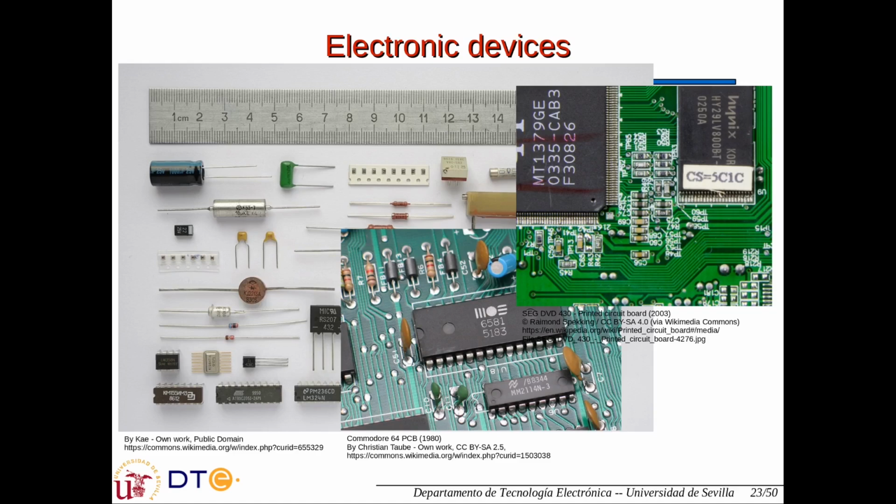So a more modern printed circuit board from the beginning of the 21st century is this one, where we also have some integrated circuits. Now these circuits are connected to the board using a technique that is called SMD, which stands for surface mounted devices. They are soldered using these very small pins on the surface, and discrete components like this one are also soldered on top of the board. The connections don't go through the holes.